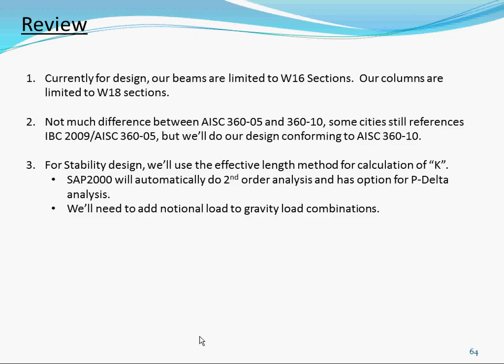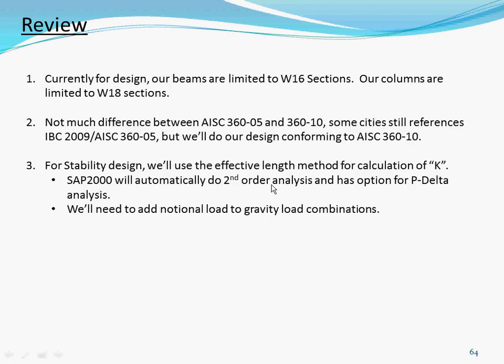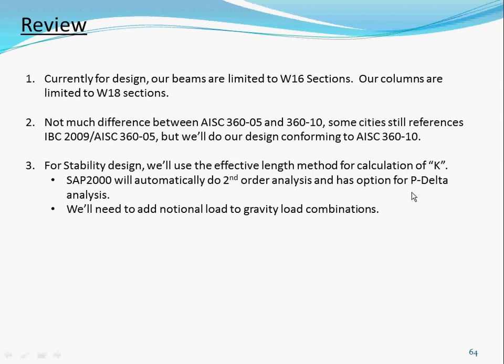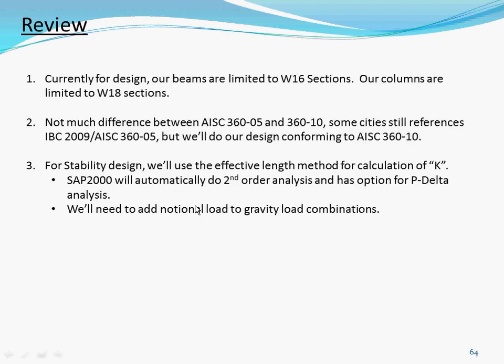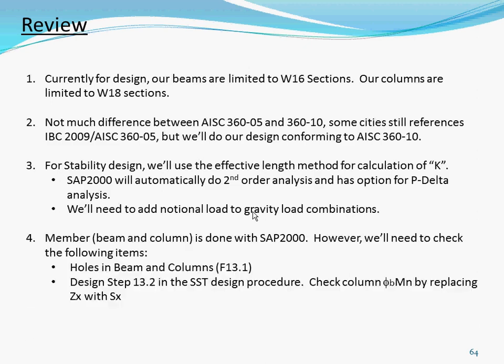For stability design, we'll use the effective length method for calculation of the K. SAP will automatically do a second order analysis, and we'll check that option to include a P-delta analysis. So that's a check. However, one thing we have to do is to add notional loads to the gravity load combination, and that's done through the load combination. I'll show you how to add in a notional load to those load combinations.